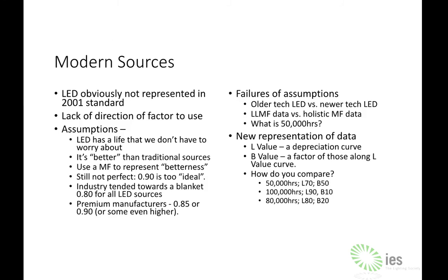I've seen even higher. Phil brought me some data today. They're saying 0.99. That's interesting stuff, because they're trying to set their product apart from others. And this is how they can say, we sell quality LED chips compared to theirs that don't. That's part of the failures of the assumption that we're comparing old LEDs versus new LEDs with maintenance factor, but we're also comparing good LED chips with bad LED chips. And all this data that we're being thrown, this 0.8 and 0.99, that's still just the LMF data, but we keep sticking it in as our holistic maintenance factor.